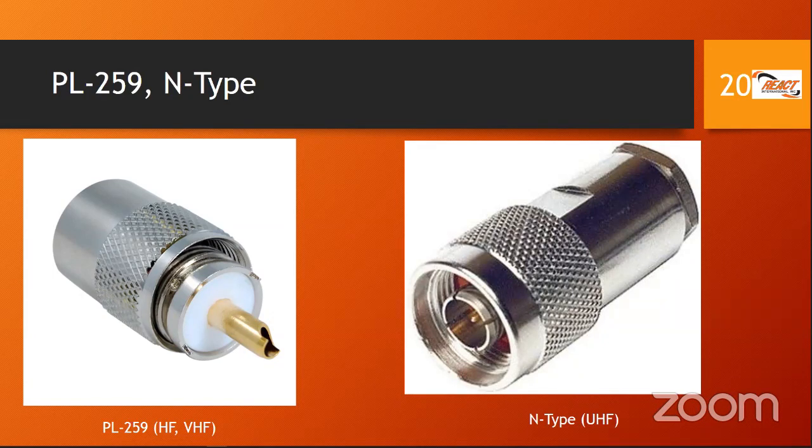And there are also lower loss thinner cables as well. That's why I said rule of thumb earlier: you want the lowest loss cable, but you also want the shortest run. For convenience, sometimes patch cords are also made using the thinner cable. If you want to connect a radio to another device, such as a meter or a tuner, and we'll come across those devices shortly, you create what you call patch cables, and you can use those for very short runs. The loss per foot or per 100 feet is a lot, but if you're using a very short length, the loss might be acceptable.